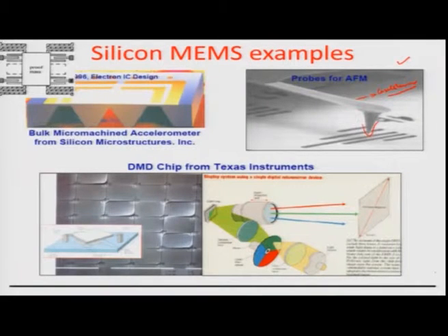And so, this understanding of bending can happen maybe in terms of a light beam which is falling on an otherwise shiny surface on the top of this cantilever beam and is subjected to deflection because of such bending. Let us say, for example, the beam deflects by theta. So, obviously, the mirror would deflect by theta by 2, and based on such bending, one can really map the progression of the tip in the z direction, and such a z direction can then be topologically mapped as a reconstructed image which would give you an idea of how the surface looks.